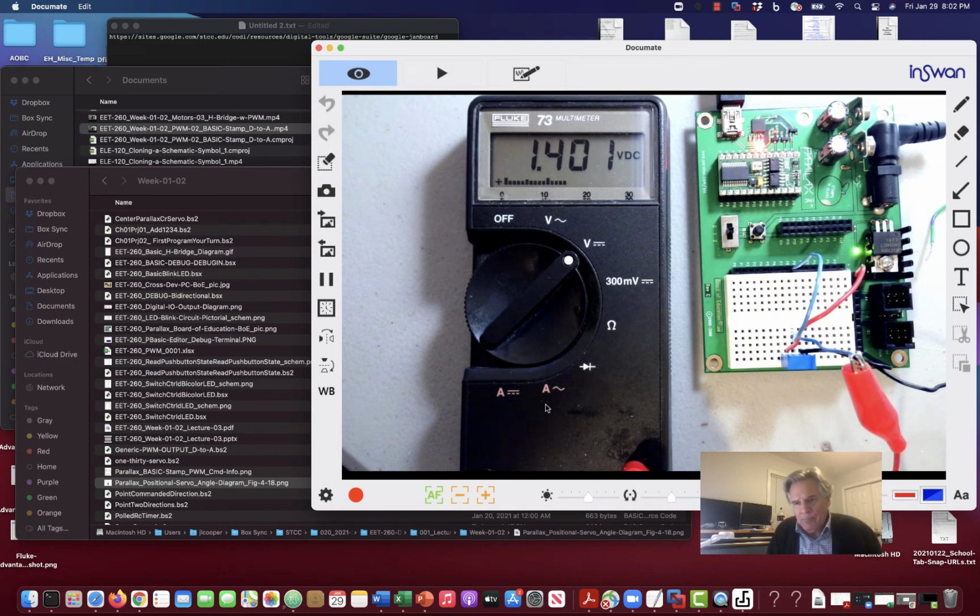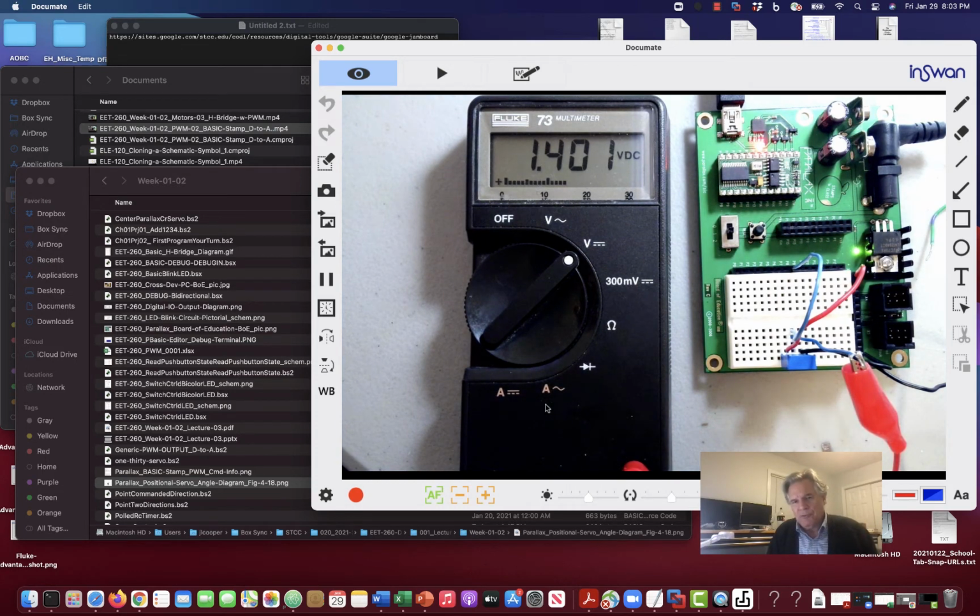So there's our experiment. There's a voltage comparator built into these digital inputs in essence, and it's right around 1.4 volts. I don't know what there is for hysteresis there. I don't think there is any. I think it's a straight threshold comparison type thing. So 1.4 is probably the number to remember for our future experiments, where we try to do things based on the threshold voltage.